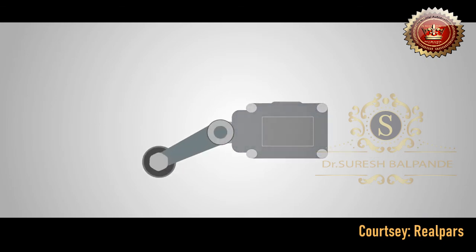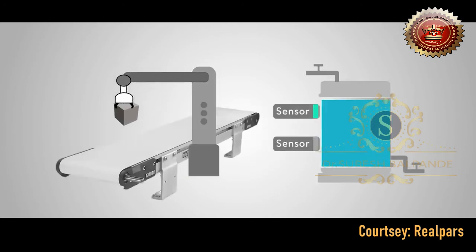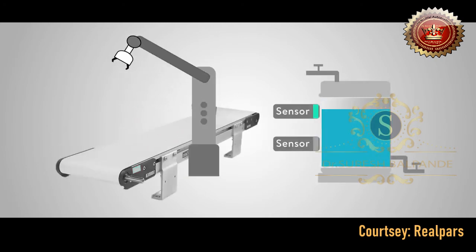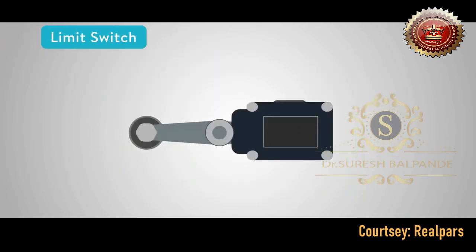Later, these became a switch that flipped when something got to a position. These are referred to as limit switches, and are still in use. We use these sorts of sensors for anything that we divide into two states: on and off, true and false, is and isn't. For example, in position, full, empty, power on, and running. Let's look at a few examples of these kinds of sensors.